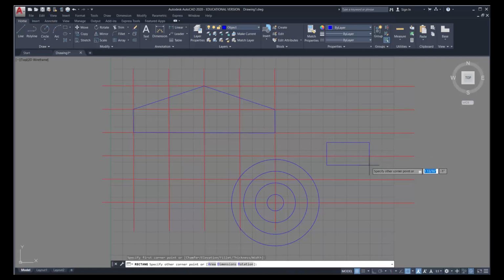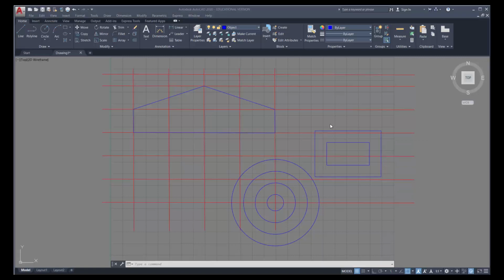What's unique about offsetting a rectangle, when I click on offset here, is that the rectangle itself, all four sides offset. Where with a line, only the single line offsets. It recognizes this as a single segment or a single element. With the rectangle command, it recognizes the rectangle as a single object or element. So when I offset that, it automatically offsets all four sides. It's a very useful and powerful tool. So let's see how we can use these new skills in our drawing.